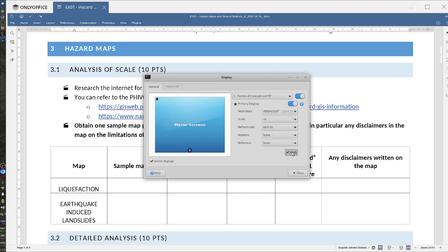or usually what T-Box does is they just measure the length of the whole active fault. For example, they have an active fault that's 100 kilometers long. So they just take 100 kilometers, then they apply some factor, because usually active faults do not rupture to their whole length. Usually it's just a portion of the whole active fault. So they just multiply it by a certain factor.